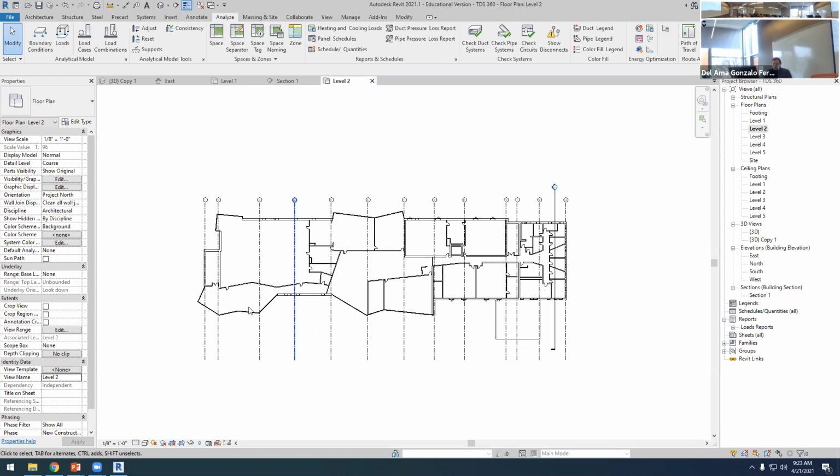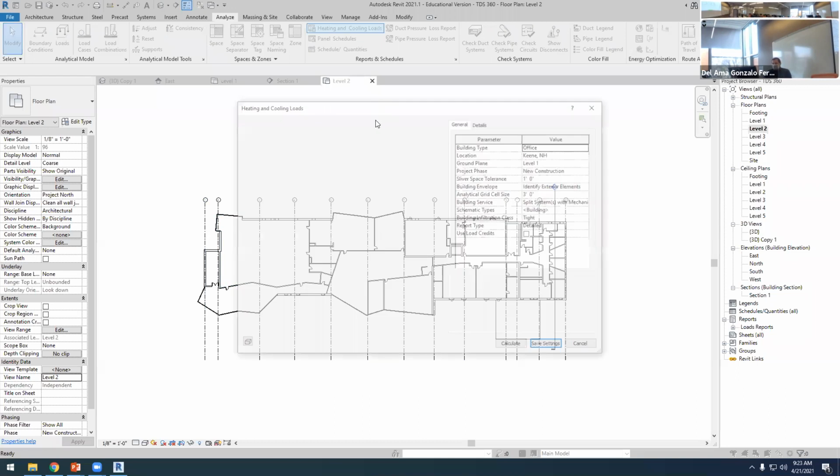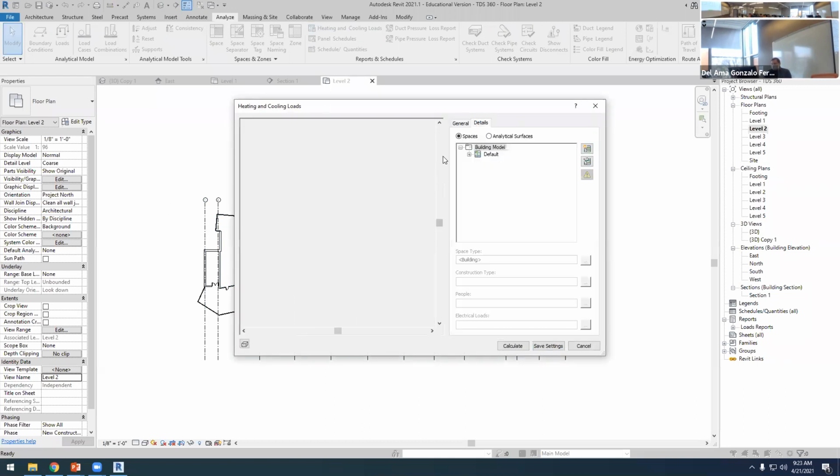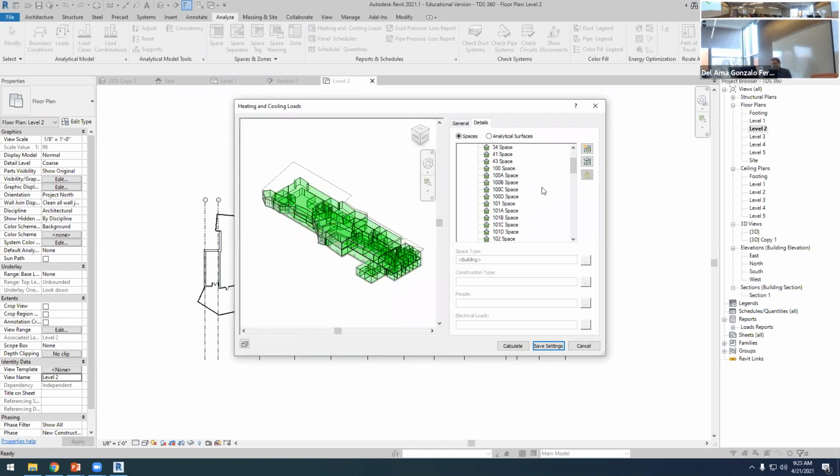If we select all the spaces in the plan of this building, it's easy because we have two different floors and we don't have double volumes. The only double volume that we have is the lobby, and we haven't considered this as a double volume. So you can select all the spaces, adjust, and then check that there are no warnings in this detail analysis. As long as we don't have any warnings here, I'm fine with this.